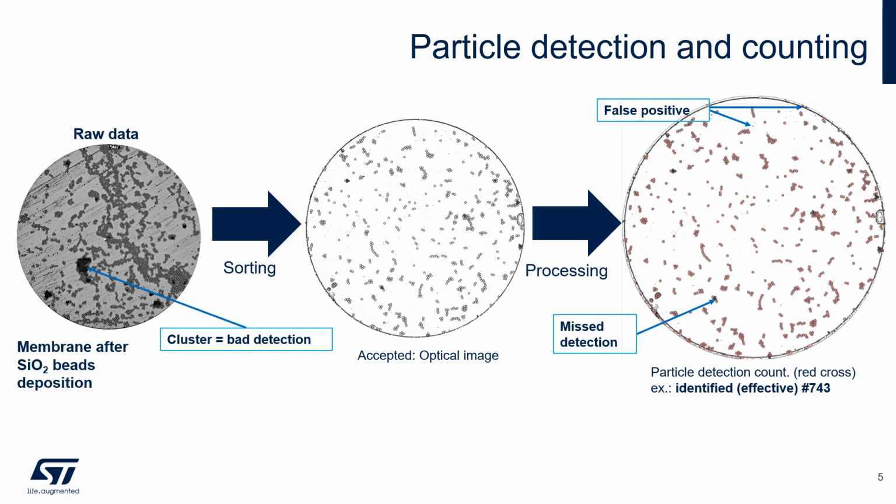We used certified microbeads to load the membrane with given extra masses for each trial. We put microbeads on top of our membrane and acquire the vibrational spectrum plus a picture of its surface. Each loading trial is then deeply analyzed and the pictures are sorted, rejecting those unsuitable to be subsequently analyzed. We derive the number n of loaded microbeads by processing the acquired images using a customized code.